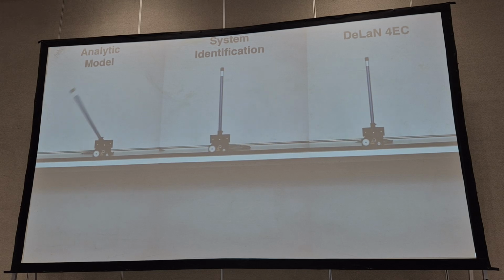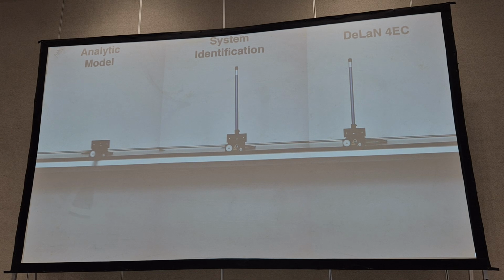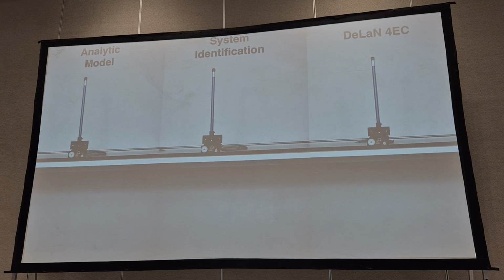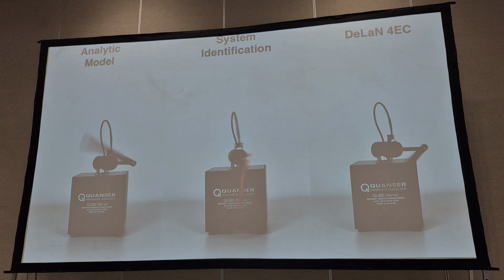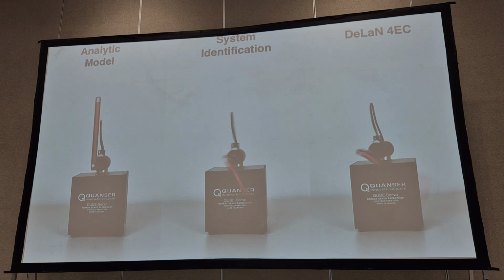And this here is just a cart-pole system, so the most basic setup where you can show these things. And of course, this one you can make work with an analytical model. This one you can make work with a system identification because it is so straightforward. Already for the Furuta pendulum, which is very short, just 2 centimeters, you're always deep into the noise. And for that reason, the system identification actually fails. And you can even show that this is partially a bandwidth problem. That all the off-the-shelf system identification methods cannot cope with that kind of data in there.